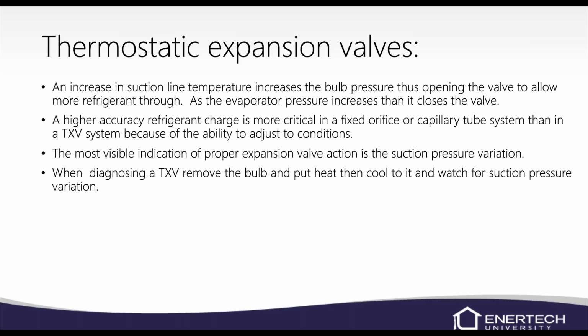We can run into high amp draws and we can actually get into a high pressure situation. I had one last week, a split unit that was overcharged by 5 pounds. It'd run for a little while, then it'd start building discharge pressure and it would go out on high pressure.